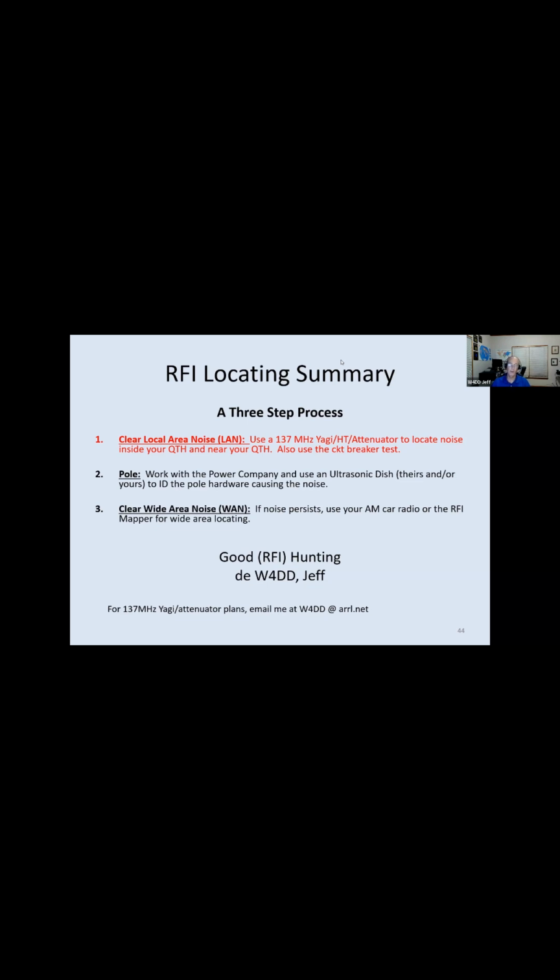Not necessarily. If you're running 500 amps or 400 amps at 7 kV through a main line, it's going to be a little warm. And the other thing was some of the parts on the pole, when you viewed the image, it was more of a cloud around each one of the parts, and the clouds kind of merged together. It wasn't very distinctive. So I didn't find the infrared views of the pole hardware too useful.